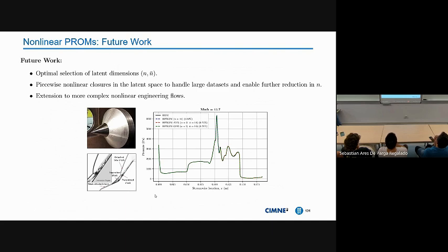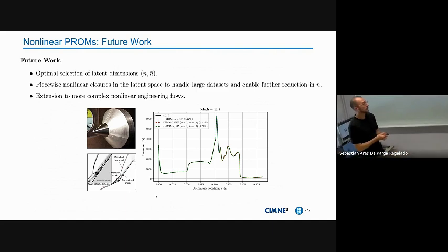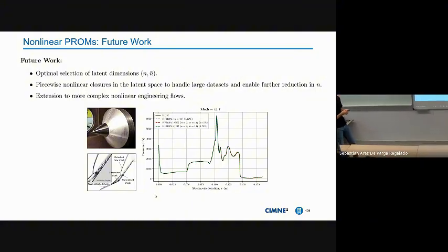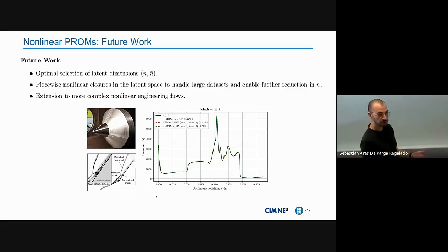Here we are plotting the streamwise location of x along this bicone at Mach 11.7, the pressure for the HP-ROM with a size of 16, which uses 16 snapshots to generate a 16 degree of freedom problem. With the HP-ROM, ANN, and GPR, we managed to get 2 degrees of freedom. However, for the ANN, it is fair to notice that we had to build 500 artificial snapshots.